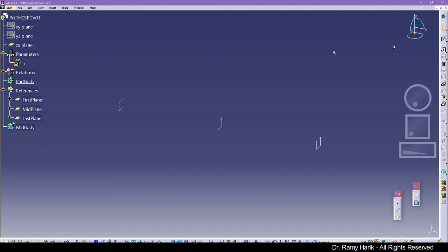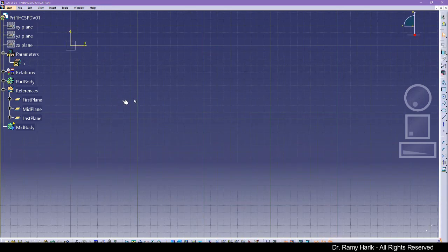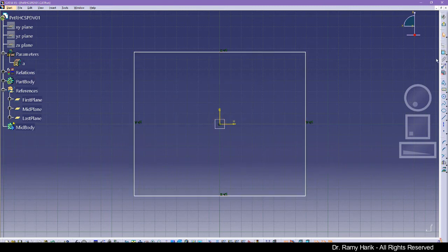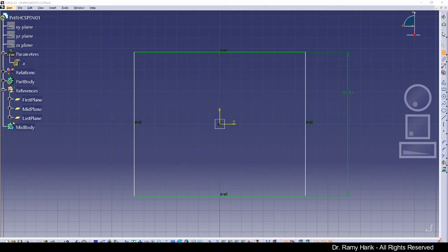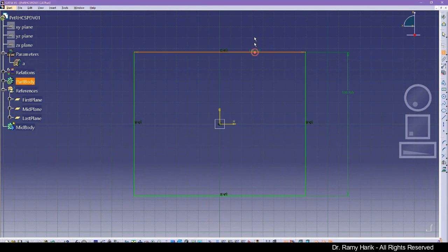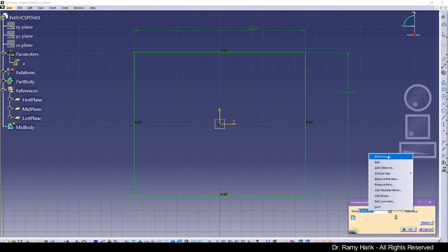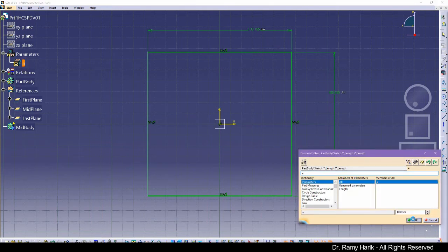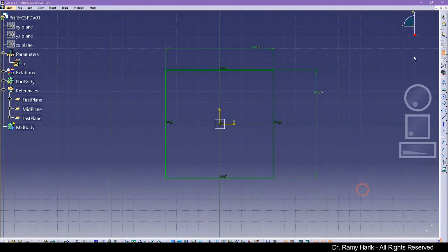We're going to start with our 2 sketches, and I'm going to hide the z-axis plane because we're going to use the first plane. So sketch on the first plane, center it, and it's going to be a centered rectangle. The dimensions are, let me see back in here because I forgot, a square of dimension a. That makes it easier. So this element, we're going to set equal to this one, and this element, we are going to set to the value a. That's for the first one.